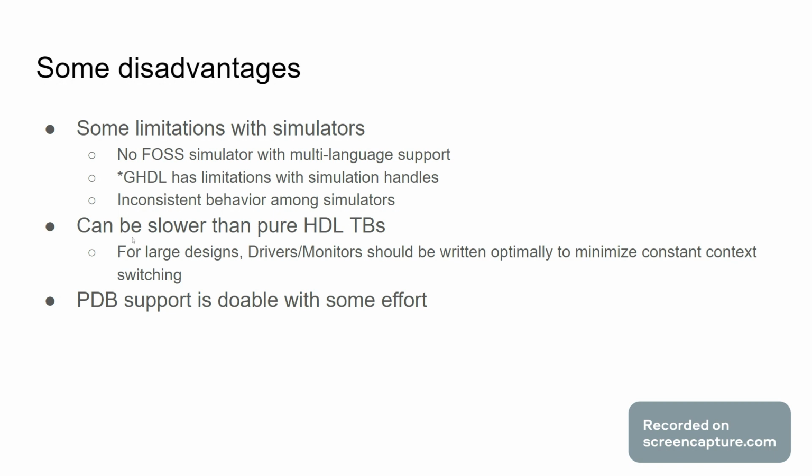This is something that needs to get tested. I know that in theory, your Python tests using cocotb are going to run slower compared to the same tests fully implemented in HDL. In fact, it is recommended that certain operations are done in the HDL testbench side, like driving clocks, because swapping back and forth does incur a little bit of overhead. When I say swapping back and forth, I mean swapping from the simulator to the Python interpreter. Unfortunately, I don't have any numbers as to how bad it is. So that's one thing to keep in mind.